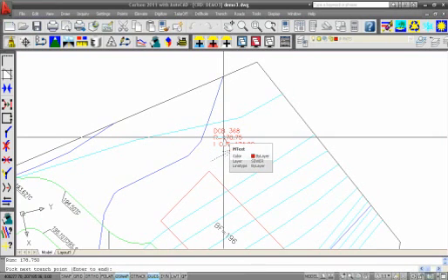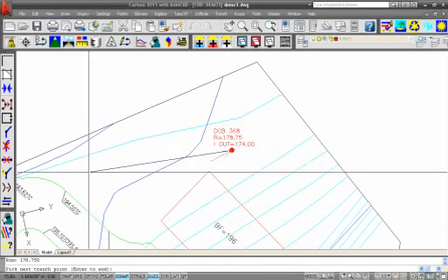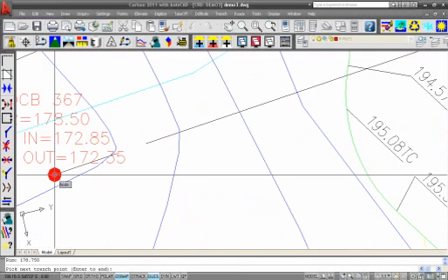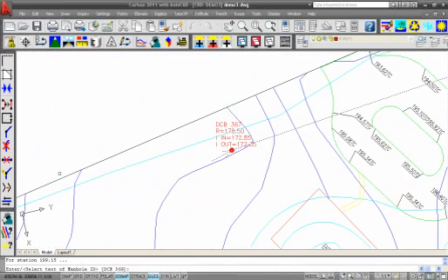And now it says pick the next point. So I can pick any point here on the drawing, and I want to go to my next manhole here and left click. Okay? Select text for the manhole ID. Select that value. You can see right above here it's reading that value off of the text in the drawing. This is something that would also work with that new PDF. If we converted all this text from a PDF, this command would now be able to work with it.